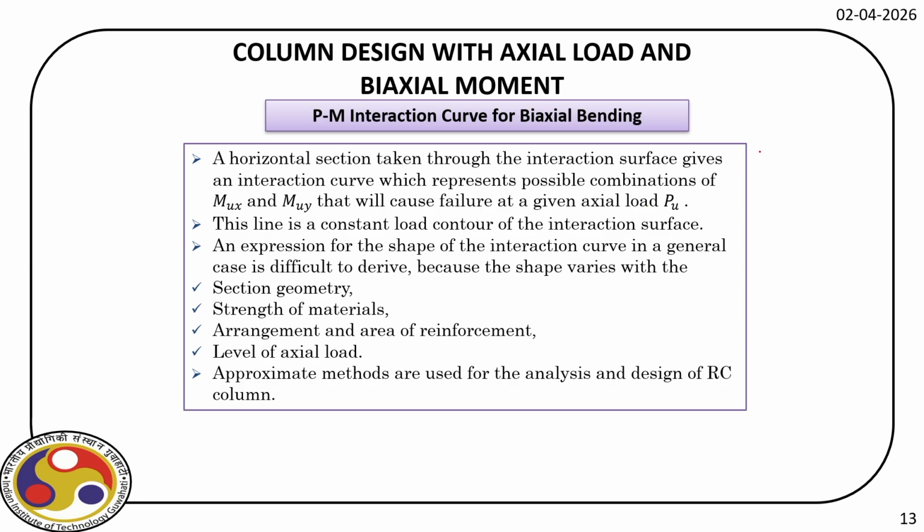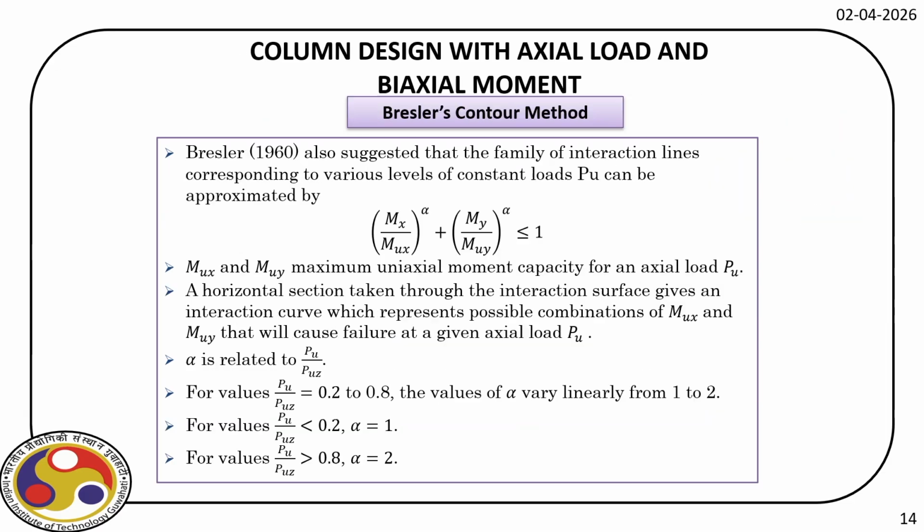So for a given cross section and the given set of reinforcement, we can develop this series of interaction curves, and then those curves are available in SP16. We'll consider an example in a minute, and then we'll see how we can use that curve to design, right? Now, this process again is iterative.